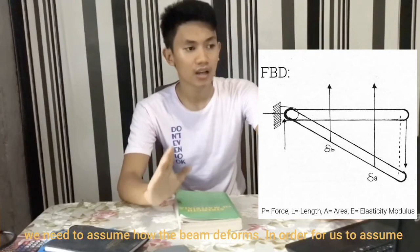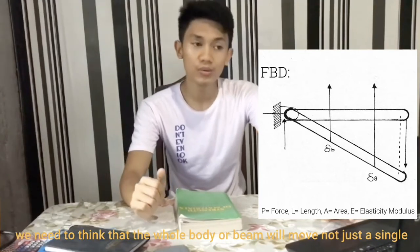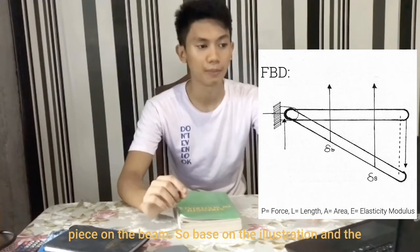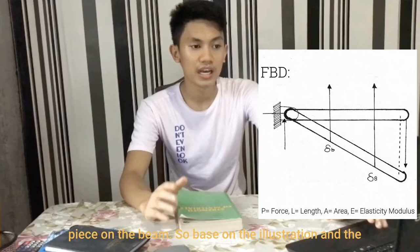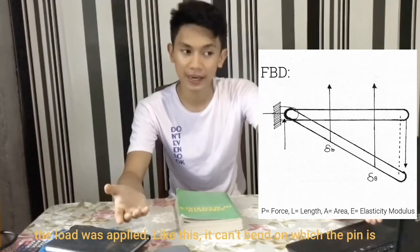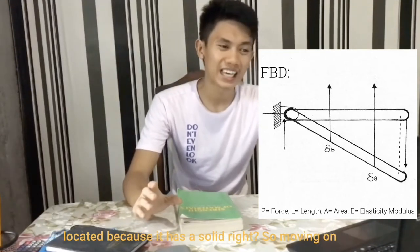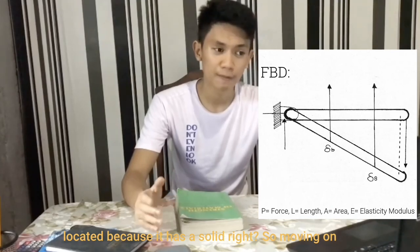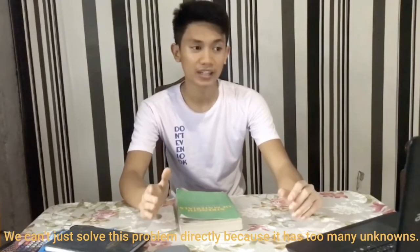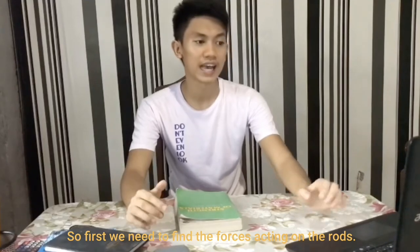After that, we need to assume how the beam deforms. In order for us to assume, we need to think that the whole body or beam will move, not just a single piece of the beam. Based on the illustration and the position of the load, we can assume that it will bend at the area where the load was applied, like this. It can't bend where the pin is located because it is solid, right? Moving on, we can't just solve this problem directly because it has too many unknowns. So first, we need to find the forces acting on the rods.